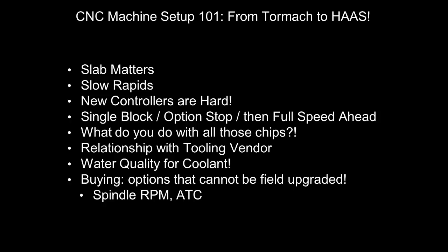The only thing I would respectfully add to what Al just said is that when you're moving from a Tormach to a Haas, let me tell you, when you're dumping 10, 15 horsepower into a part through a tool, work holding is really important. A friend of mine who just bought a VF4SS Haas unfortunately within the first few weeks threw a part because he didn't realize how much more horsepower you're putting into it, and it ripped it out. So otherwise, what Al said is right. Normally, you crash when you're calling up a tool or starting an operation. I would argue that that is also an operator error, not applying enough clamping force and value to something like adaptive clearing. You see that cut start, you know what the overall load on the part is once the cut starts, and then things kind of normalize after that.